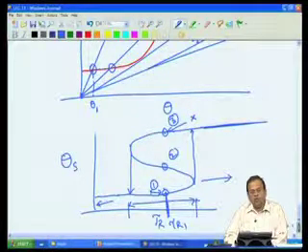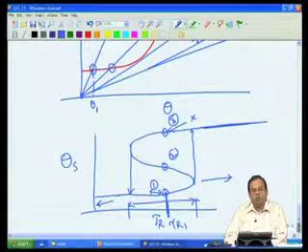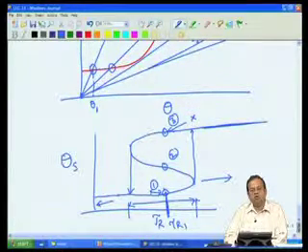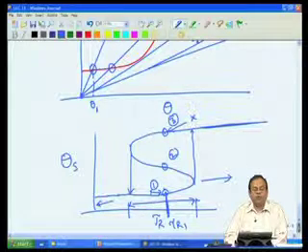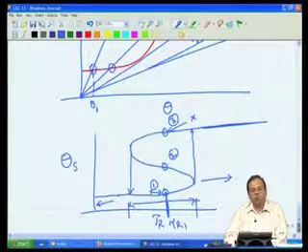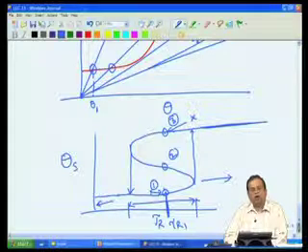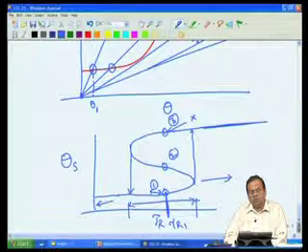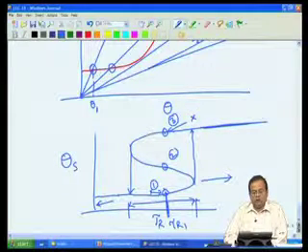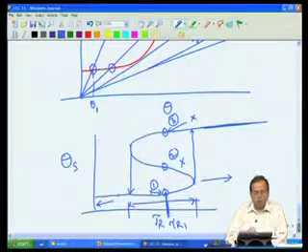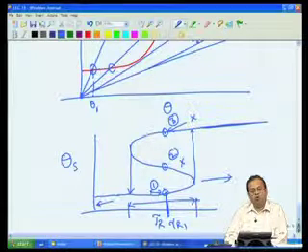So, it all depends on where you start your reactor. In other words, for a stirred tank reactor, even though you are interested in steady state, what steady state you will get will depend upon where you start up your reactor, and therefore, startup of the reactor is also an important aspect in deciding how the reactions will take place and what steady states we will get. The second question that one would like to therefore ask is, what happens if I start over here at this particular value of temperature? Will I go to steady state number 2, because that appears to be the closest steady state?